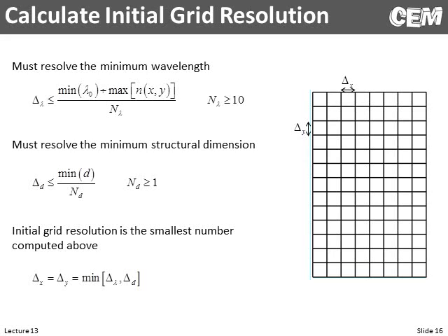you'll model your device and you'll get an answer. Then you'll increase the grid resolution. Use more points. It'll take a little bit longer, but you resimulate it, and you keep doing that. You keep adding points and simulating your answer, and then you'll plot your answer as a function of number of points in the grid. And what you'll see is that answer will swing around, but it'll eventually converge, and it's kind of up to you to figure out where it's converged. And very often you could add more points and get better accuracy, however it's taking a long time.